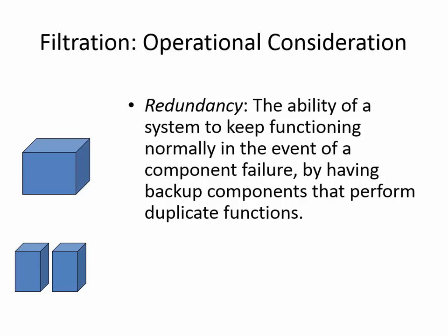And we want to produce water continuously, all day long. And the backwash cycle maybe only takes 30 minutes or an hour or so. But even still, when you're going to the trouble of making a water treatment plant, you don't want it to just be temporarily offline. And so if you had 3 of these, then that means this one can be backwashing and cleaning the filter, and these 2 are still operational.